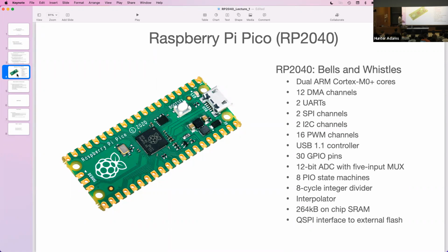The programs that you write for these PIO state machines, you write in assembler, a custom assembly language called PIO assembly. It includes 9 instructions. I won't ask you to do much of that. You're going to use PIO programs to do things like drive a VGA screen. They're incredibly powerful for building custom high-speed communication interfaces from the RP2040 to some other device.